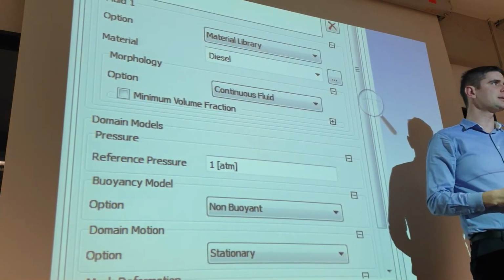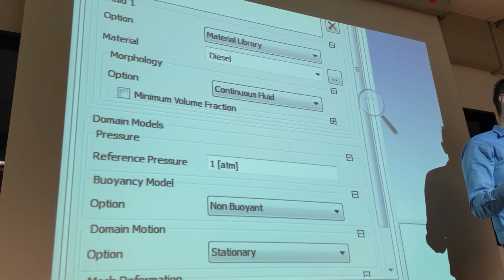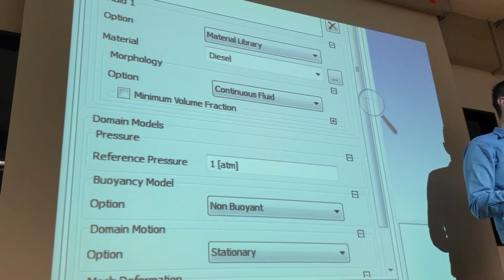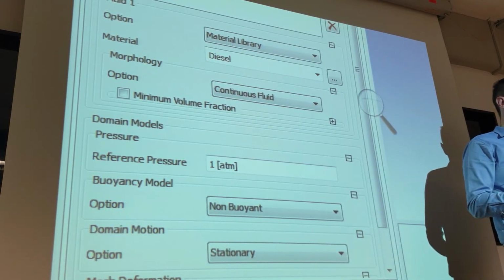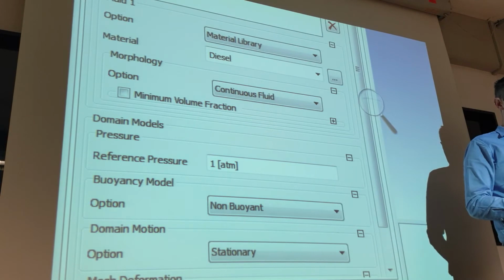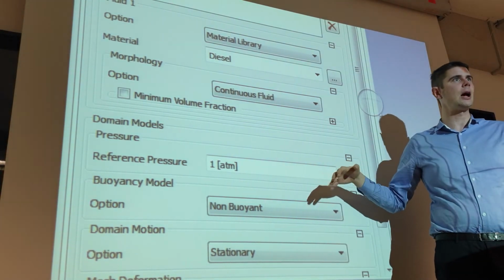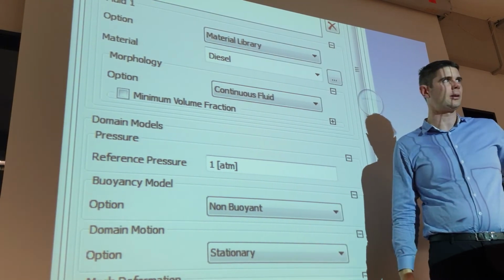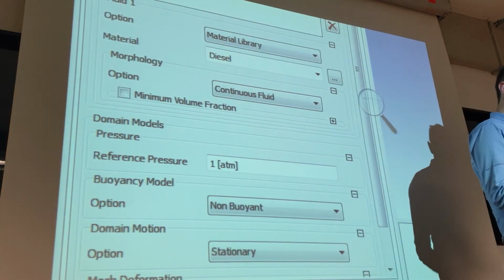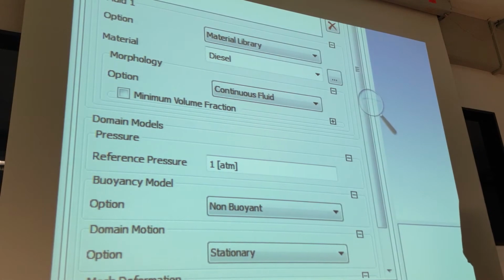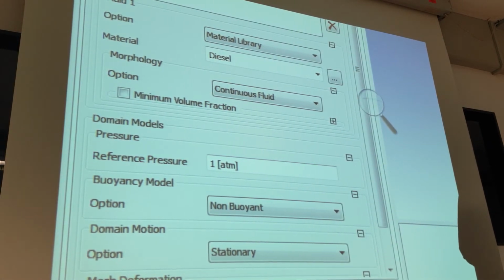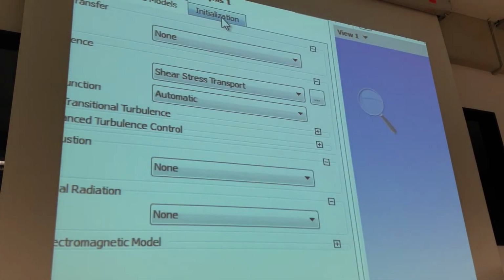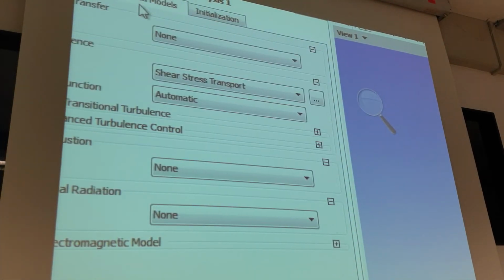Like by measurement, yes? If you make a measurement, you will see 0 at 1 atmosphere. The sensor tells you 0 pressure. So 0 means 1 atmosphere. So it means vacuum is 0 atmosphere in reality. It means in the program it is -1 atmosphere. Yes? It means -1 atmosphere pressure is vacuum. So, okay, we have now 0. It means 1 atmosphere pressure is outlet.